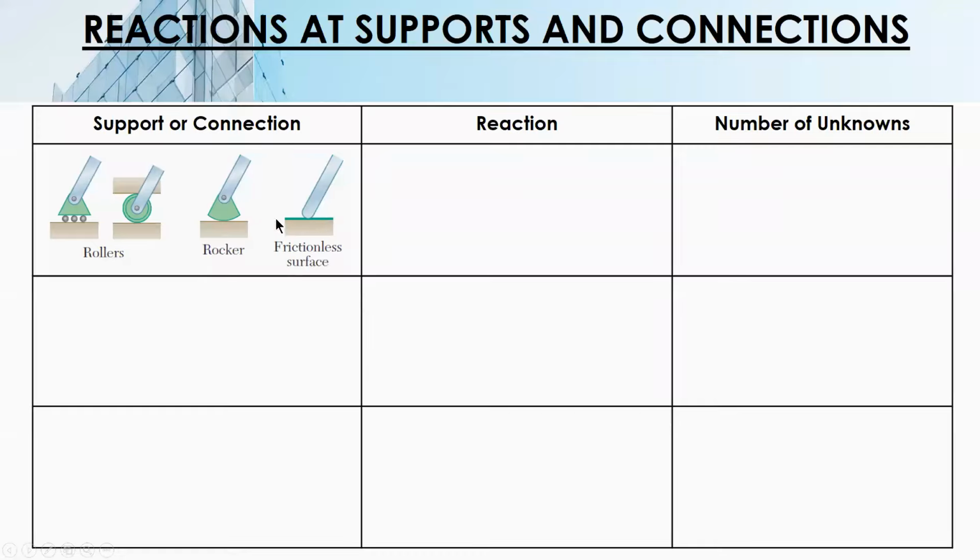Horizontally, it can almost slide, since it's frictionless. In Y, it cannot. So therefore, its reaction is this one. You only have one reaction with known line of action. Known line of action is the reaction is perpendicular to the surface. It's not vertical. Perpendicular to the surface.